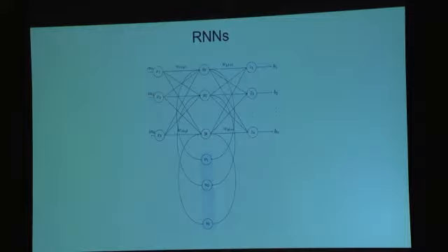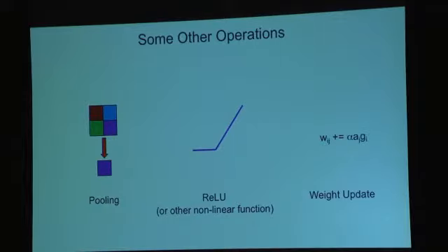For speech networks and certain natural language processing networks, we see a lot of recurrent neural networks. And these are really just fully connected layers where we've folded them back on themselves. So for each of the elements of this recurrent layer, in addition to having connections from the preceding set of activations and the next set of activations, they have connections back to themselves via a set of activations that basically form a short-term memory for the network. But for the sake of the processing demands, the hardware requirements of doing recurrent neural networks are basically no different than doing a fully connected layer. Now we do need some other operations to plug our network together. You need to be able to do them and not have horrible performance on them, but they tend not to be limiting.